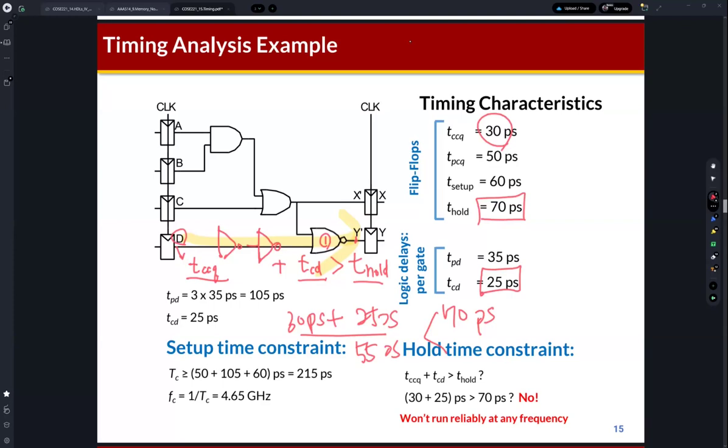If we just add inverter gates in the path, the value is the same at this point, but the delay is increased because there are more gates. So if a hold time violation is detected, we can add inverters.